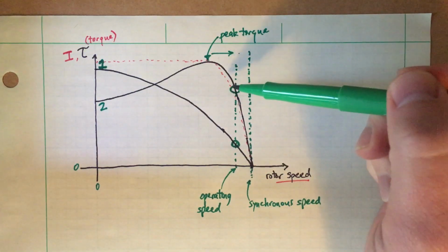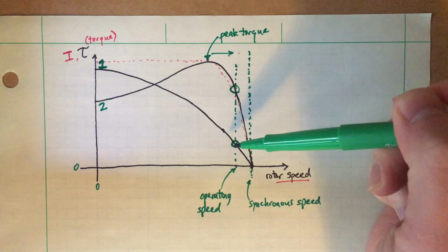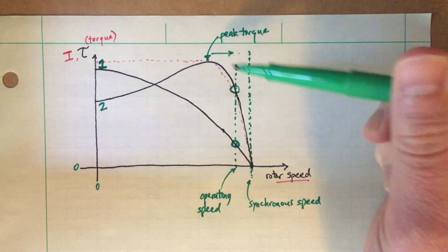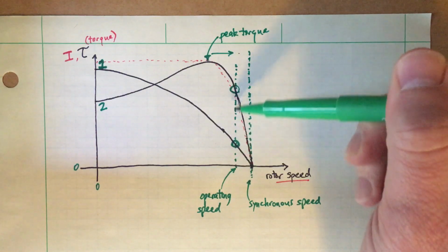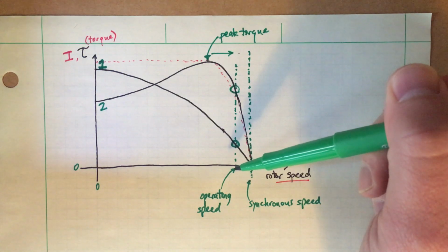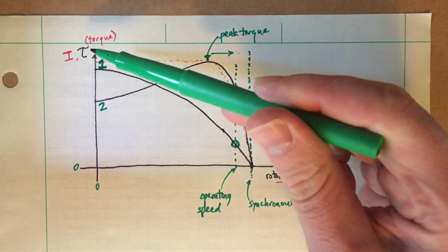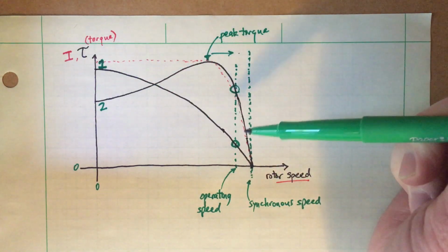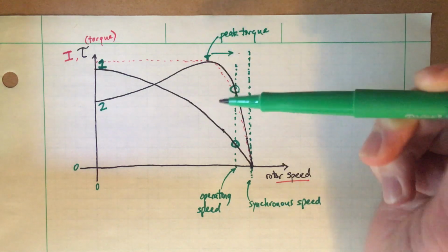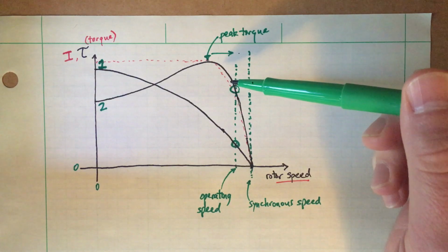But in any case, whatever that operating speed is, not really that important, okay? But what you want in a motor is when you get more resisting torque. In other words, remember, this is the torque that's being produced by the motor. And if you're operating at a steady speed, that means that the net torque on the motor must be 0, right? The resisting torque must balance exactly with the torque developed by the motor, and then you're not changing your rotational speed, right? You'll just stay at this operating speed here, okay?